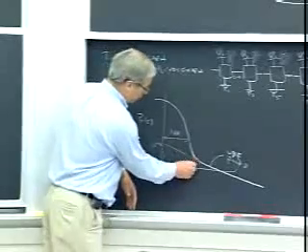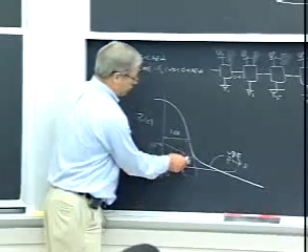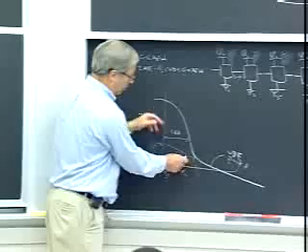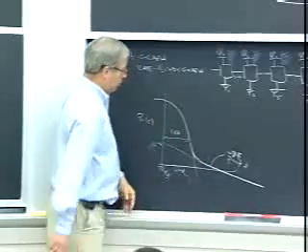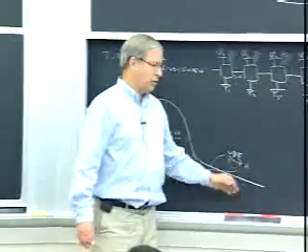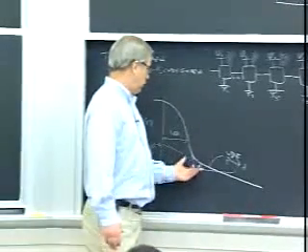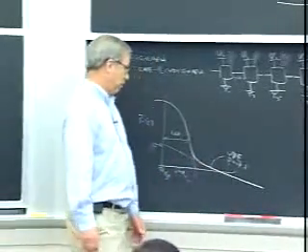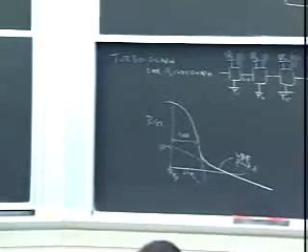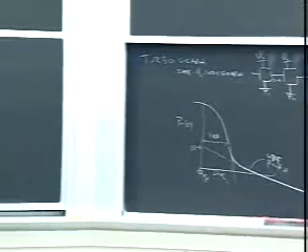but then at some point it becomes dominant. You can think of these as being 2 types of curve. This is the iterative decoding curve. This is simple maximum likelihood decoding when you have minimum distance of d with a small error coefficient. And so this error floor is an important issue for turbo codes.